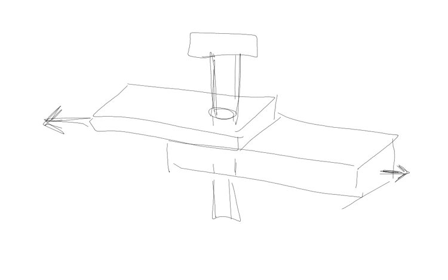Well, you can see that right at the junction where these two boards meet, this screw is actually being torn apart. This bottom half is being pulled towards the right, and this top half is being pulled towards the left. So right at that junction, that's what we call a shearing plane, because that's the plane at which this screw is being basically split in two.